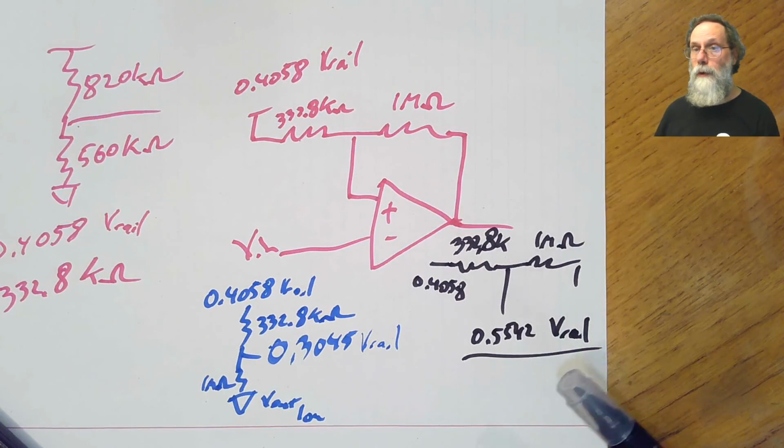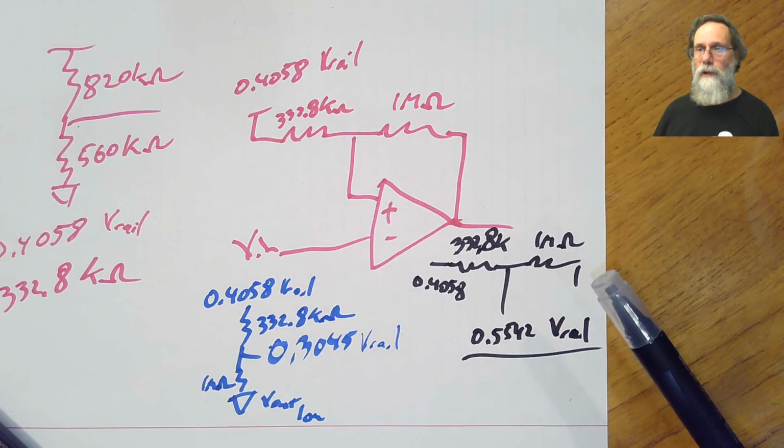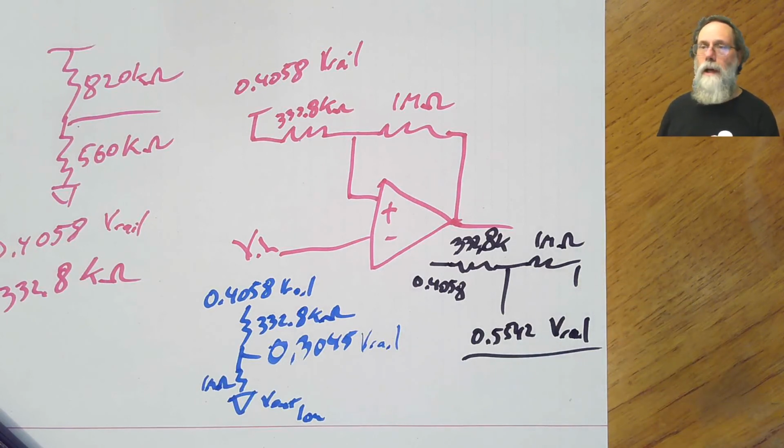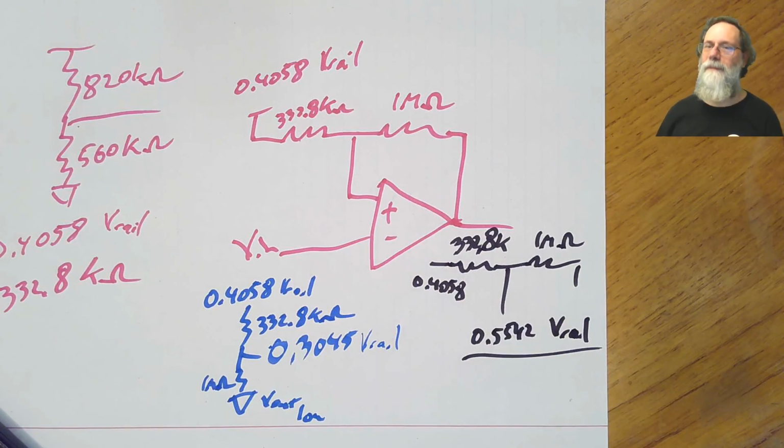So it's a fairly straightforward thing, again, to do the calculations you need. Picking the resistor sizes is a little trickier algebra than before, but still not very difficult. So both inverting and non-inverting Schmitt triggers are fairly simple circuits that are easy to do. And remember, I never want to see feedback to a positive input unless you're doing a Schmitt trigger. In any other situation, it's a complete failure and I'm not going to stand for it. So no positive feedback except Schmitt triggers.